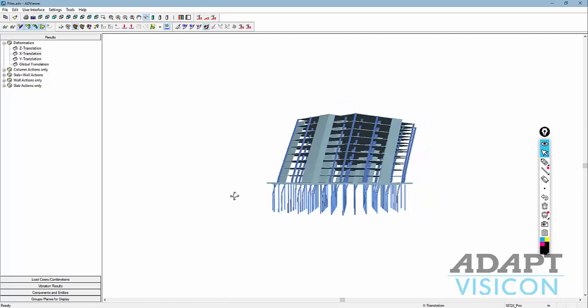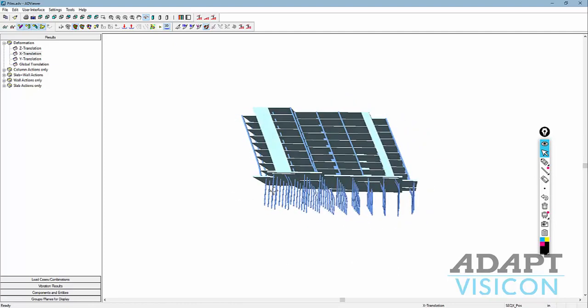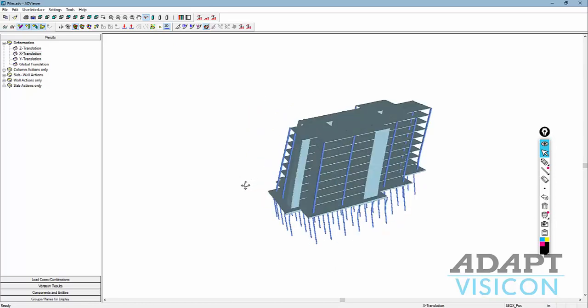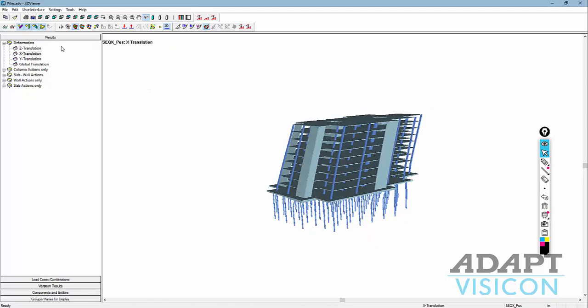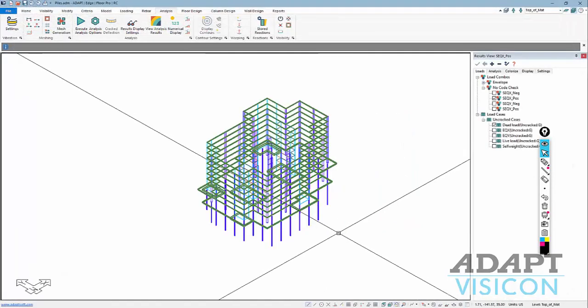And you can see there's some interesting behavior going on down at the base of the piles, especially where we have walls and large displacements near these walls. We could do the same for Y direction, for Y loads, etc. So one thing you can do is just check the global deformation just to make sure that it might be within expectation, make sense for the input that you've made into the model.